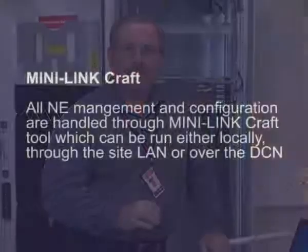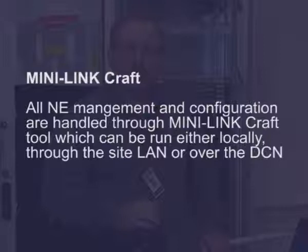Make sure that the local craft terminal software is correctly set up and that the Minilink Service Manager software is installed on the computer if it is required. Later versions may be configured via the USB port using a normal web browser. Refer to the Minilink Traffic Node Operation Manual and the Minilink Service Manager Installation Guide if you need more information about requirements and installation instructions.